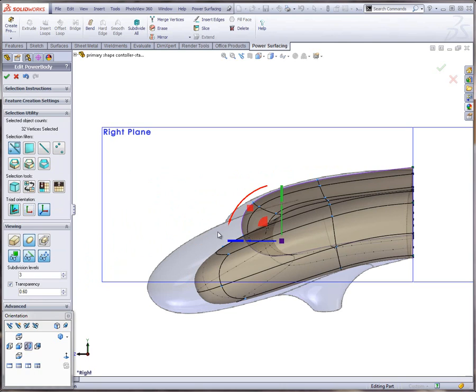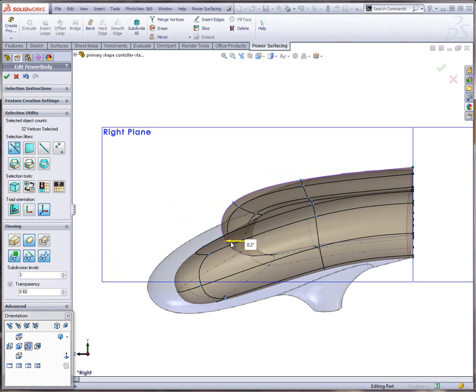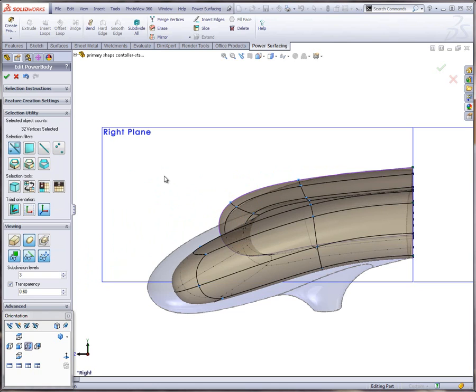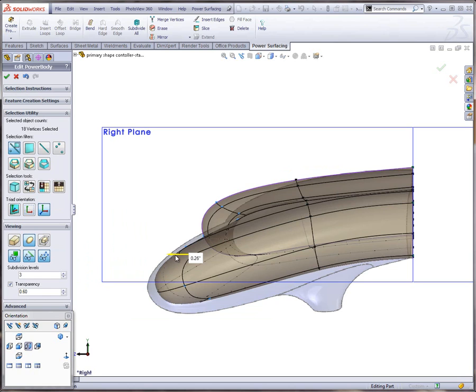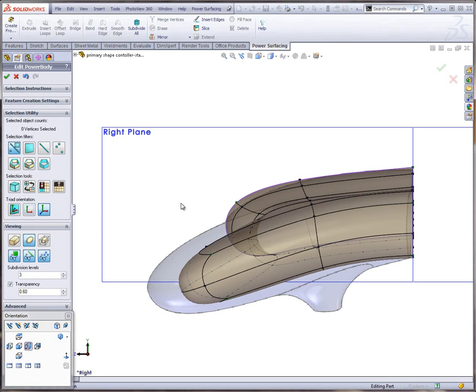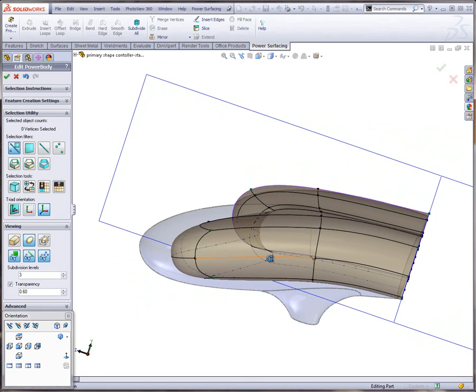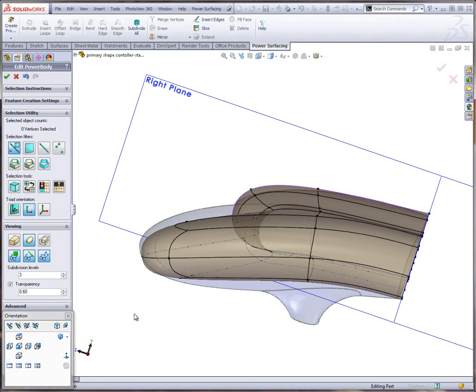And now with that selection still there, I can actually pull out these. Let me make another selection just for these and pull them out. Actually, I don't want to really pull out all of that. I want to probably now pull out just this part. But one thing I like to do is just rotate my view using my Alt key, standard SolidWorks type of procedure, then select all of these, and then go to screen orientation for my triad. So now I can pull these kind of in a normal direction. Okay. And we can go back to my right view.